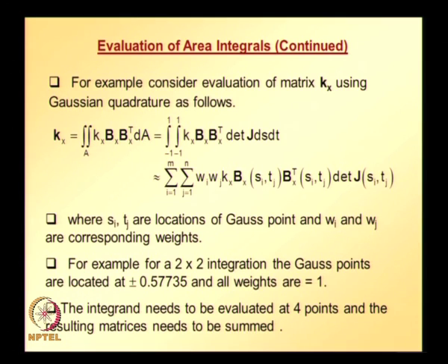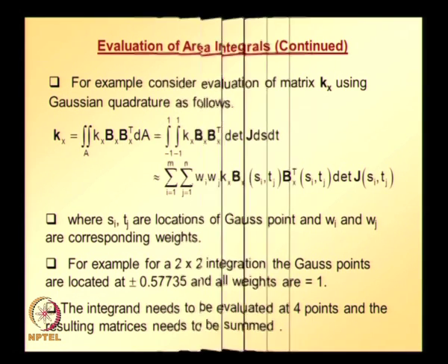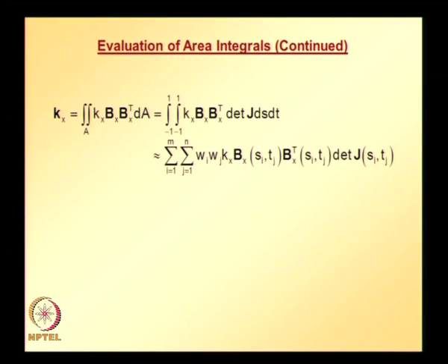First we need to express this kx in terms of S, T before we go ahead with numerical integration. How to express kx as a function of S, T? For that we need to use isoparametric mapping, which relates x, y to S, T. So, let us take a problem and try to understand various steps in the evaluation of the area integrals.